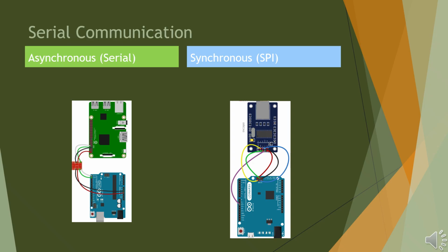A simple SPI example code initializes the SPI bus, sets the CS pin, and transmits test data using SPI.transfer. This demonstrates synchronized high-speed data exchange, far faster than asynchronous serial communication. SPI is widely used for high-performance peripherals like displays, ADCs, DACs, or Ethernet controllers. It offers high-speed and full duplex operation, though it requires more pins than I²C.